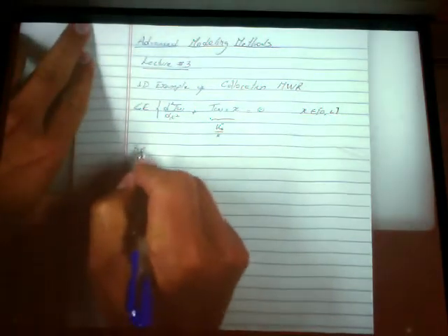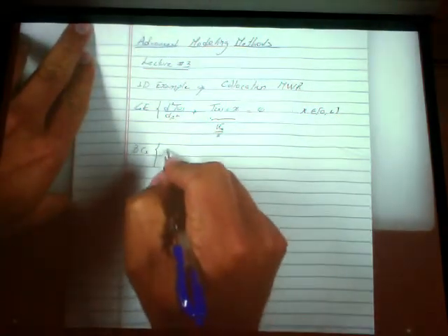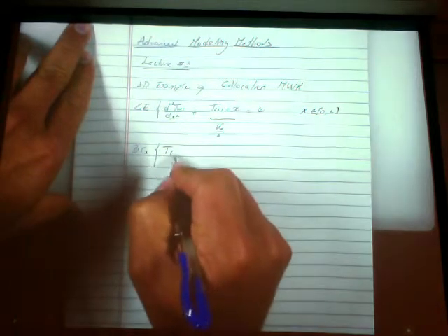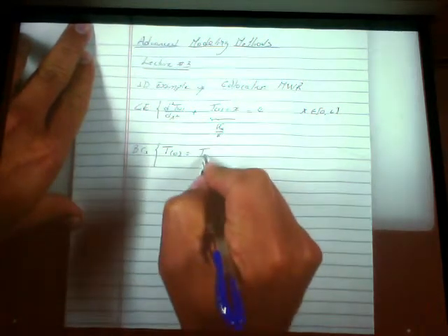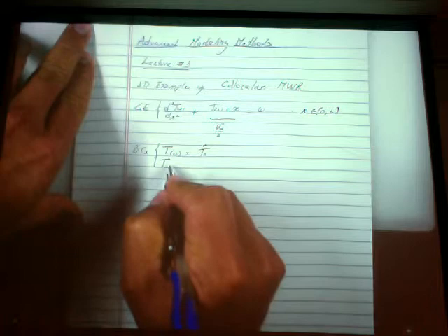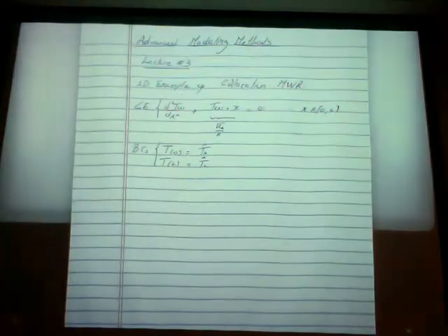Now the boundary conditions that we will use, we're going to use first kind boundary conditions on both sides. So that the temperature at x equals 0 is some T0, and the temperature at x equals L is some TL. And remember the hat I use to denote that this is a provided value, it's a given value, it's imposed.